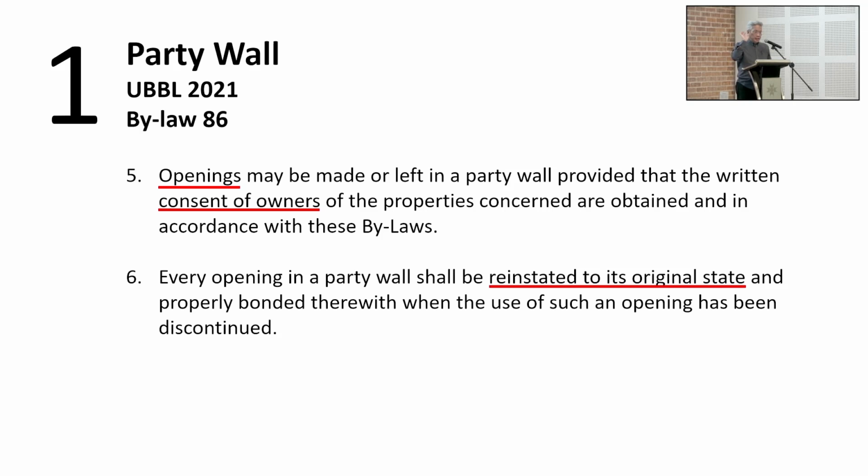Right? So here the takeaway is this. A party wall is a legal definition. Its purpose is to provide privacy, of course, visual privacy, acoustic privacy, but most important, as far as we are concerned, that 100 millimeter thickness of a material, a solid material. Okay, full stop. That is the physical legal requirement of a party wall.